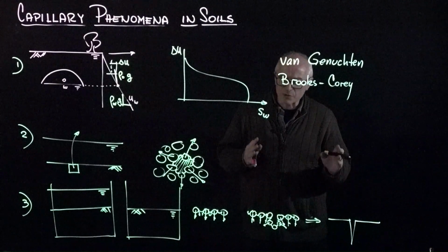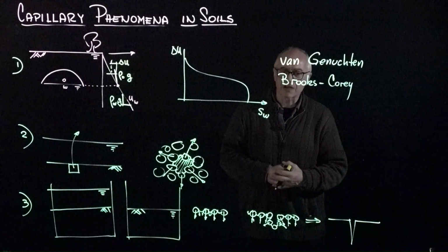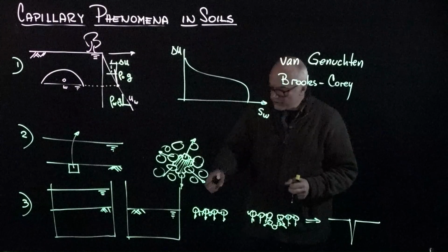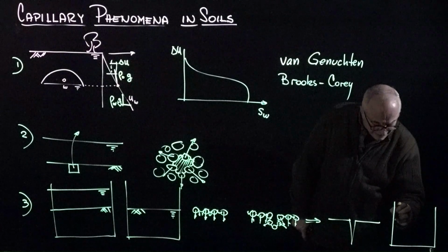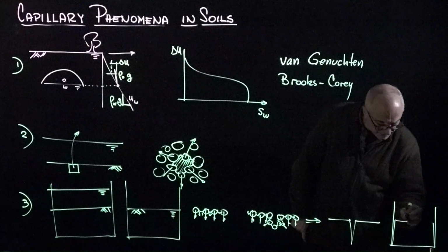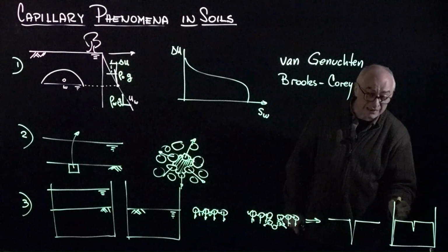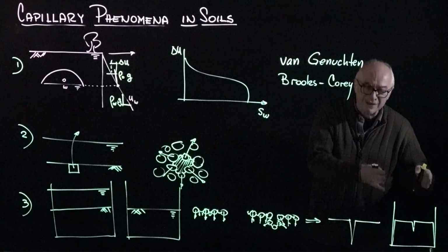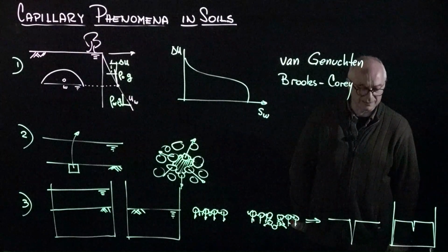Desiccation crack, for the most part, is primarily the invasion of the air-water interface through the largest pores into a soil. In fact, if we go back and look at this container carefully, very likely this container will show a desiccation crack that forms peripherally around the wall first before other desiccation cracks. Why? Because the pores near an interface tend to be larger than in the soil, so these side walls are the ones that are invaded first, and we tend to see that extensively in experimental studies.